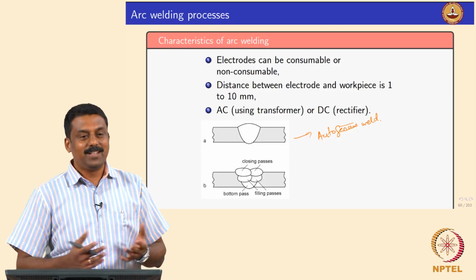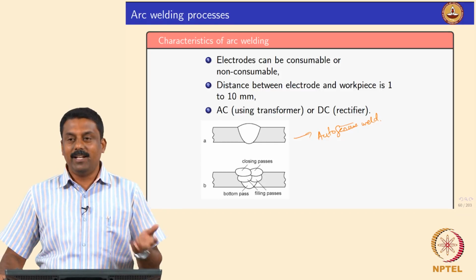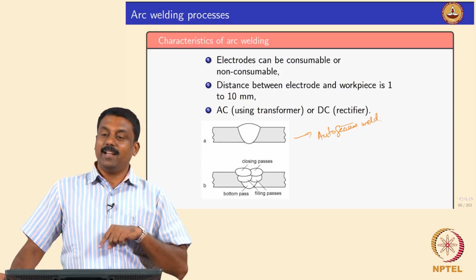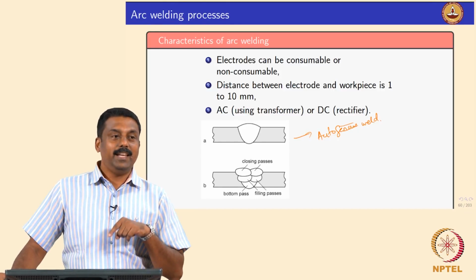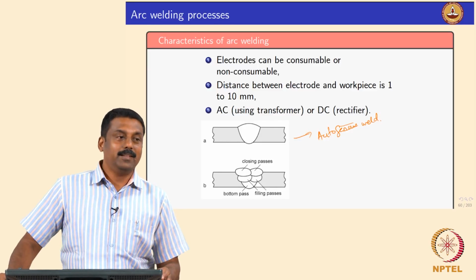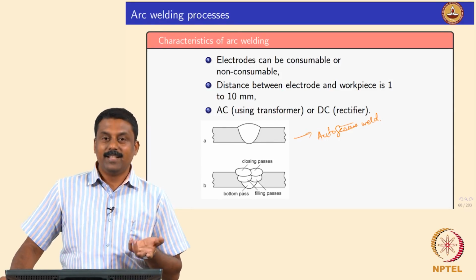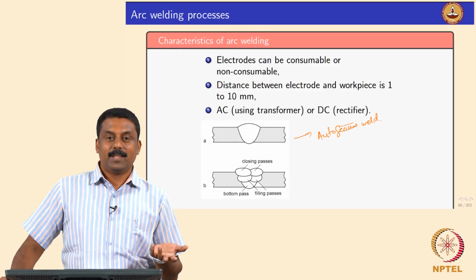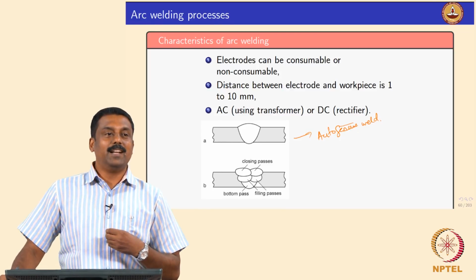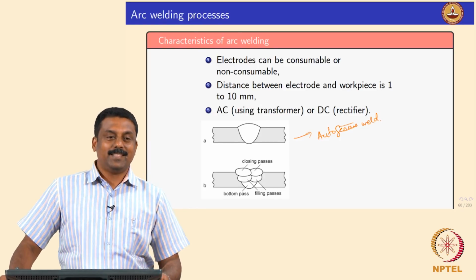So, the voltage. Again that is also important, voltage in a welding process is a derived quantity, is it not? So, what we calculate here is E, that is the field strength. So, that is the current. So, voltage is a derived quantity. When you want to control the process, you always change the current. So, voltage is a byproduct. That is why when you say that you welded, you never say you welded at so and so voltage, you always say so and so current.